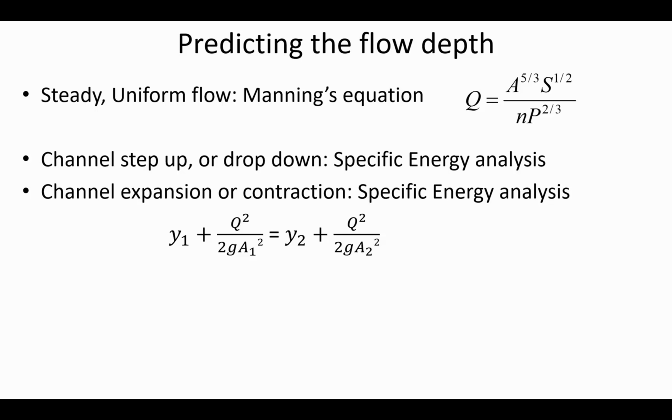And so our method there was to assess whether we had super or subcritical flow upstream, and then downstream, the reaction to the change would be interpreted by, we set up these cubic equations, found the roots, and then we'd know which root to select based on whether conditions had previously at the upstream location been supercritical or subcritical.